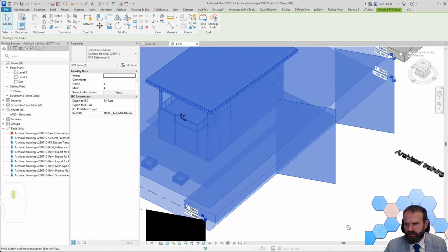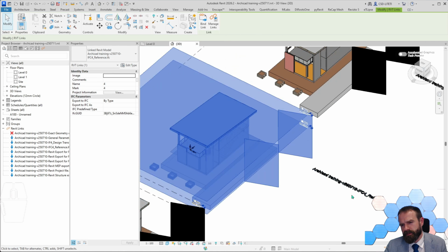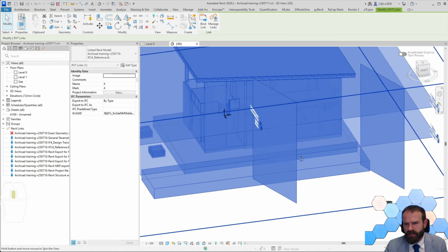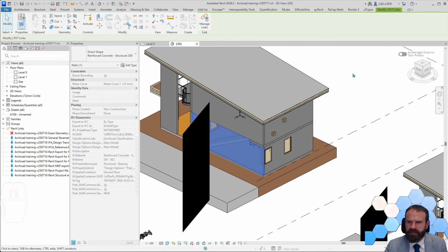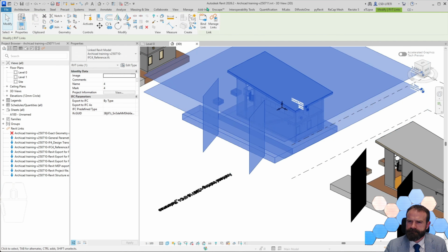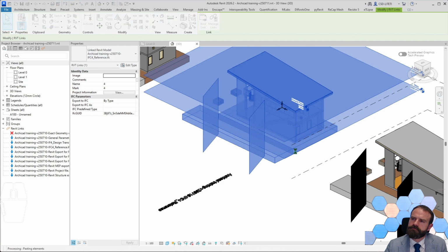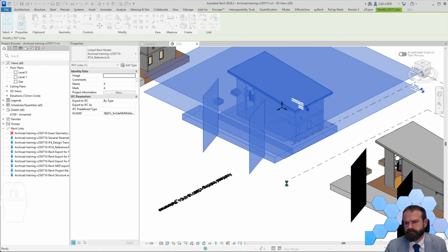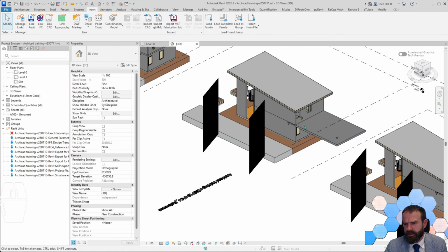So here we have the option of reference IFC4. So soil is not exported. If I select elements, they are direct shape elements. And if I click bind, I have the same problem.